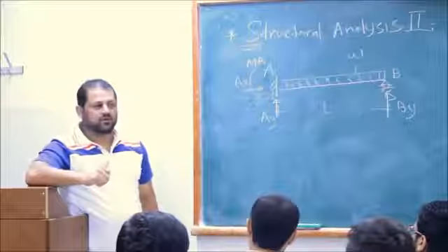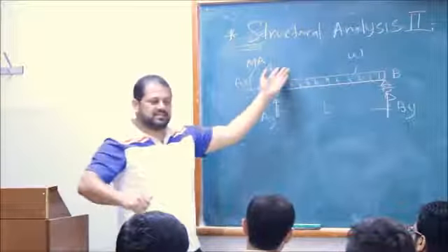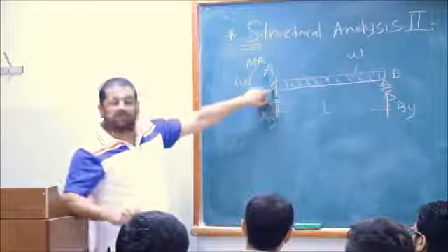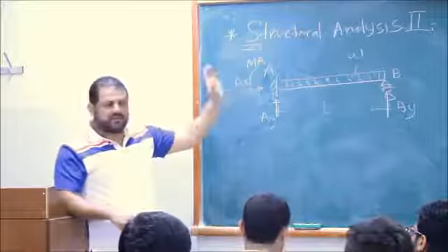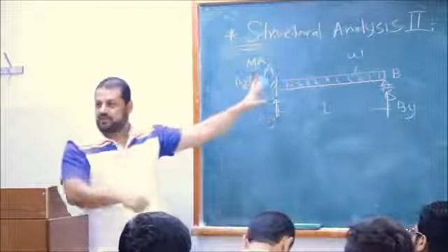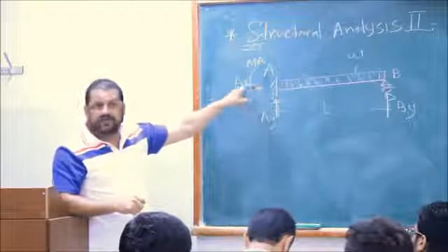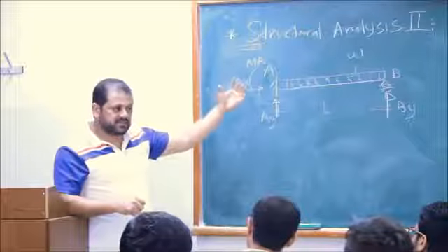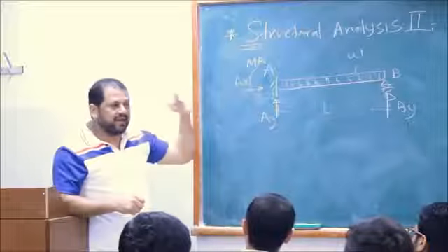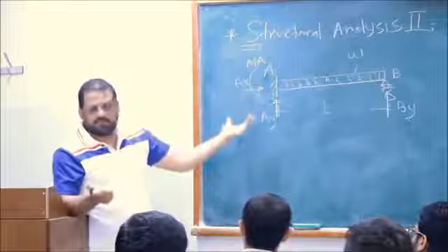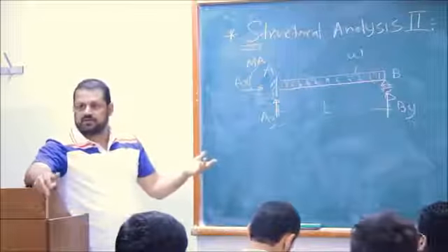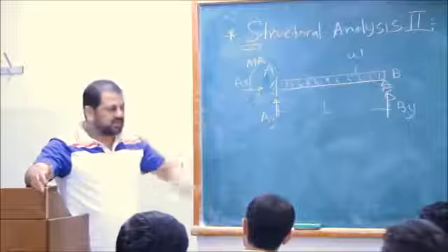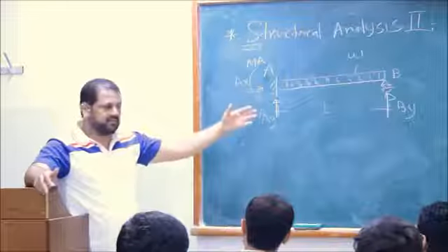Costly. It's not easy to just come and build this as a fixed support. A fixed support can cost ten times as much as a pin. A pin is just a bolt, but to make a fixation you need welding and more work. Okay? It's costly. Indeterminate structures are costly. Unless you have to, if you have the option, why would you make them indeterminate? Just make them determinate. But sometimes we are forced to have them indeterminate.